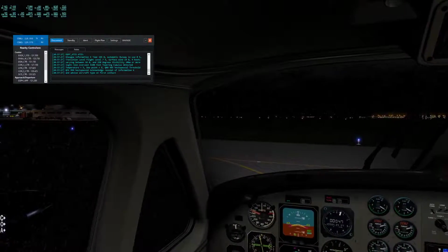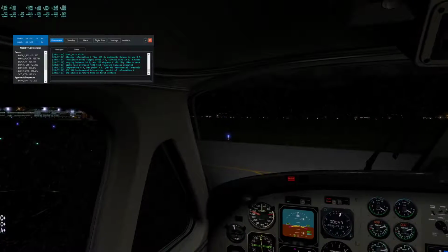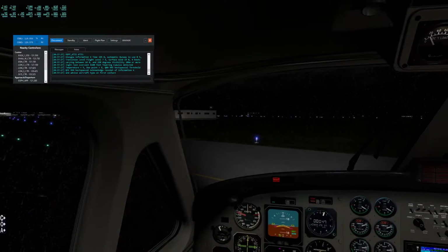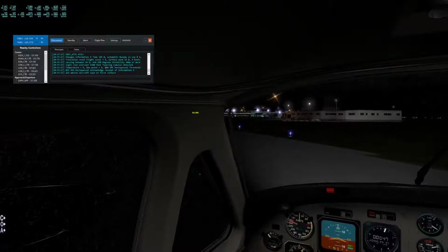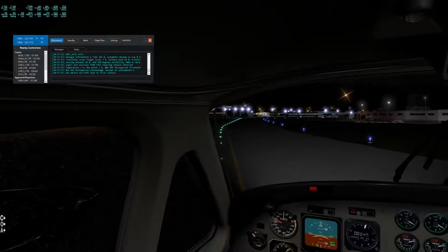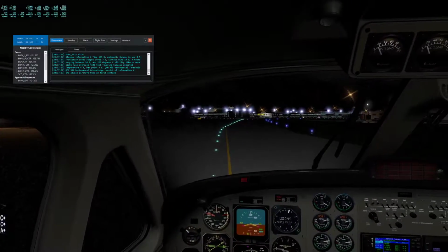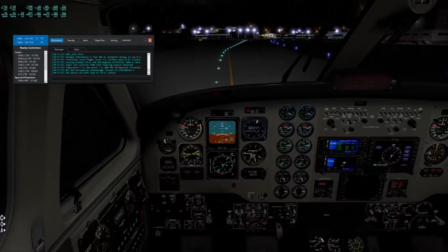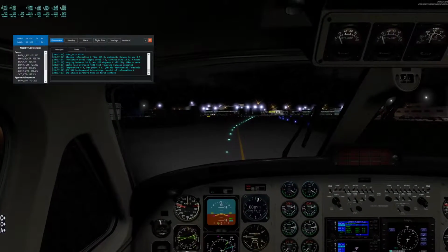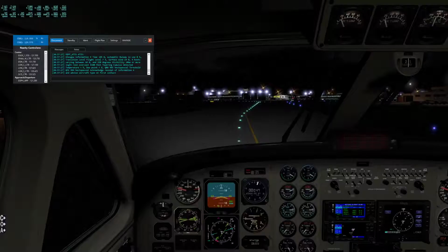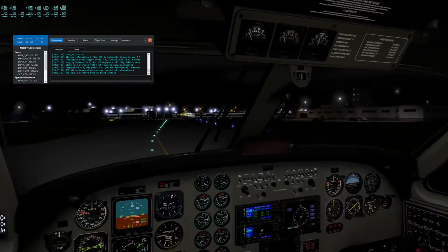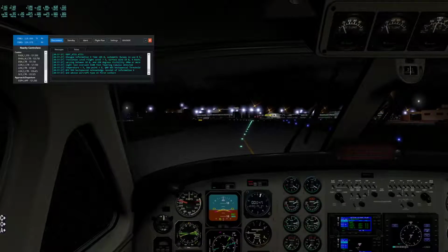And of course this is the type of aircraft that can most likely handle that fine. It doesn't need a particularly long takeoff run. But I've done no calculation to see what the minimum takeoff run is. I don't know exactly how much runway there is left. I've kind of looked at the total length quickly on the chart, 2,600 meters. That's a bit more than half, so at least 1,500 meters. And I know I can take off from the runway in Wick, which is 1,800 or slightly below that. So I just say okay.